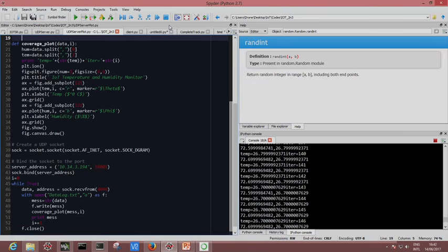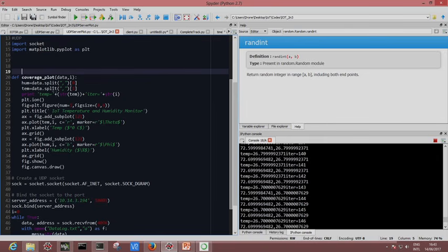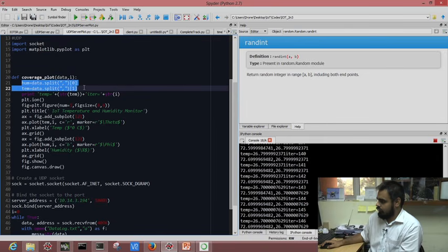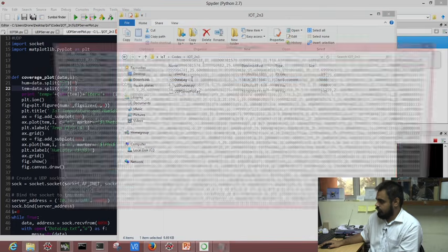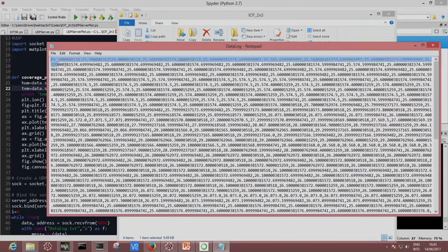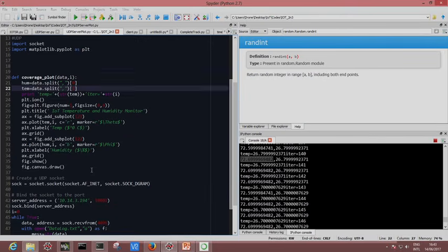One more thing you notice is, in the previous examples, your temperature and humidity values were coming in concurrently. Now in this one, since we have split the data into these parts, we have a separate temperature component, an iteration number, and a separate humidity component, which is saved in the same data log. The data log is still the same, only the scripting part has changed. So this will help save you a lot of effort.